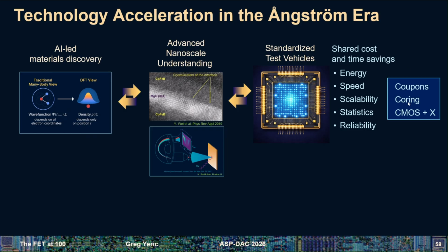So if you go to the lab up at the Pickle Research Center for UT, most university research labs are running 4-inch wafers. From a cost standpoint of tools and everything, you can take a 300 millimeter wafer and just cut a 4-inch wafer out of that. In fact, multiple 4-inch wafers. That's called coring. So that's the program that we had all ready to go in my last job.